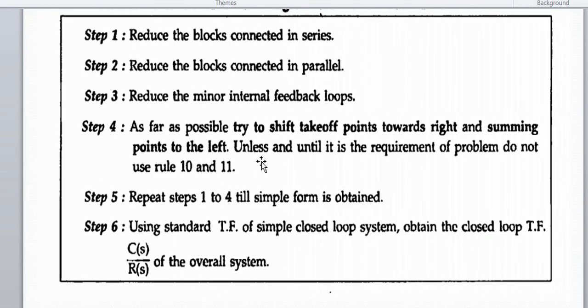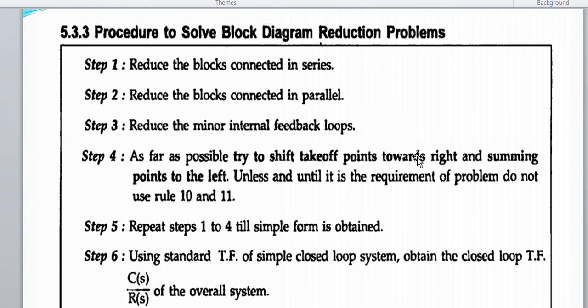Now I will go to the procedure to solve block diagram reduction problems. When you have 11 rules, how to apply those rules? Those are the guidelines given in this procedure. Step 1 says reduce the blocks connected in series. Whenever you look at a block diagram which has to be reduced, see if there are any series blocks first. Reduce them.